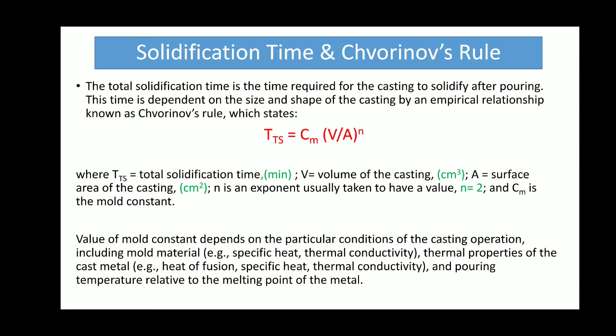Similarly, we must have complete solidification and cooling. After that only, in an expendable mold process, we break the mold and take out the cast. Otherwise, if solidification is incomplete and you break the mold and take out the part, the whole thing will be a wastage. So we must know about the solidification time.